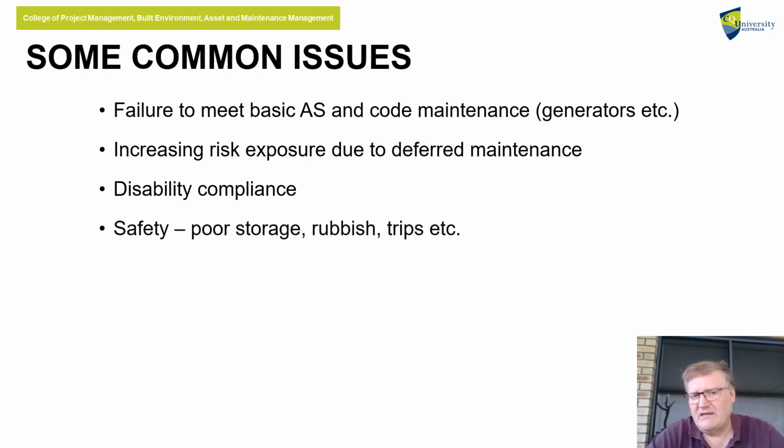Common issues again, you'll find safety. You'll find stuff stored poorly, rubbish piling up, cleaning not up to standard, signage may be out of date or broken, and I can go on with this. Again, that's a difficult one to do. I would often find furniture and boxes and that stored on the ground floor level, tucked underneath the fire escape staircase. Now, could be a fire risk. It might be blocking the escape door. So there's all that sort of stuff.